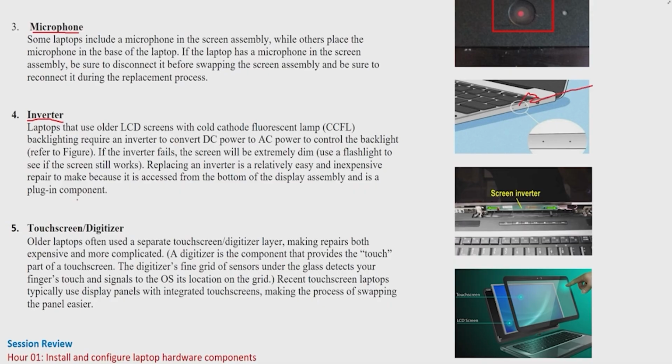Sometimes people are always connecting power; they say that when we unplug the power, my laptop is not working. There is no issue with the laptop. Your LED is fine, your laptop is fine, everything is fine. You just have to look at this inverter inside. If that inverter chip is not working, then the battery will not give you power. Whenever you unplug the power, the screen will go off. Your laptop is working. Sometimes it is giving sounds that the RAM is working or the CPU is working, but the display is not coming. That means your inverter chip is having a problem. Just open it, remove this chip, go to the shop and tell them that this is my screen inverter. Please give me the replacement.